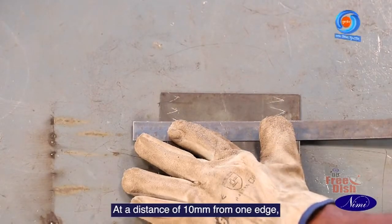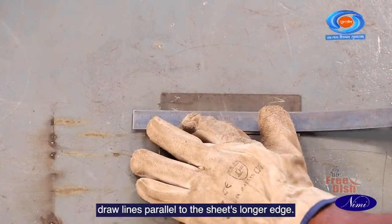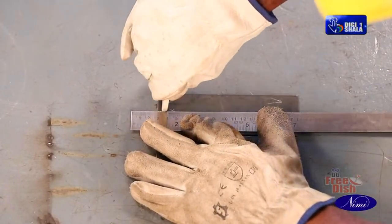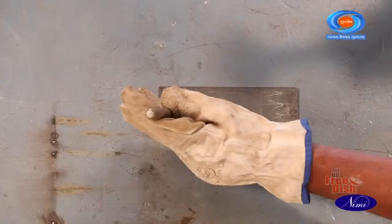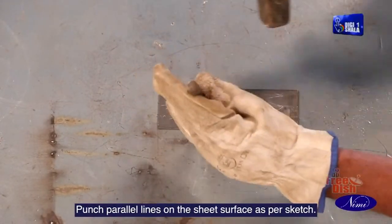At a distance of 10 mm from one edge, draw lines parallel to the sheet's longer edge. Punch parallel lines on the sheet surface as per sketch.